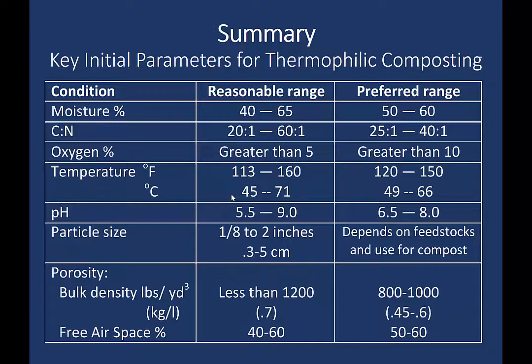The other thing you can do is do volatile solids, which I talked about in the other presentation, which is basically your organic matter. You put it in a furnace, and it's what leaves you. So it's the difference in weight between before the furnace and after, and that's your organic matter. And then you test the nitrogen, and then you call it a CN ratio. So they're probably doing that. They're testing the volatile solids and calling that C, which is approximate for C. And then they're testing the nitrogen, and they're giving you a CN ratio versus actually using a CN analyzer. So I'm assuming that's what's happening.